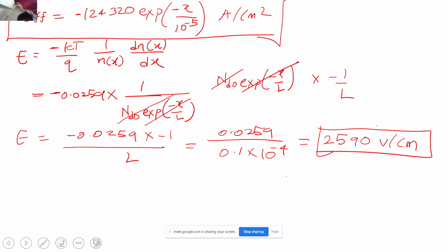See, I can take a case of non-equilibrium statistics. If you simply pump electron hole pairs in a semiconductor, say I shine light on it, I can create a lot of electron hole pairs and I will see diffusion of carriers. In that case, will there be an electric field? In that case, you will not. There will be diffusion and eventually, for an electric field to be there, you need to have the background doping. So basically the space charge has to be there. Only when you have space charge will you have an electric field.